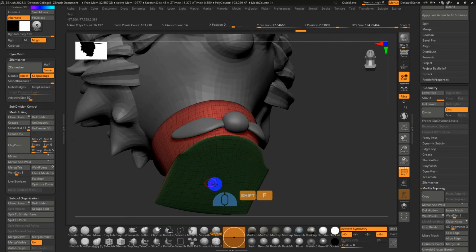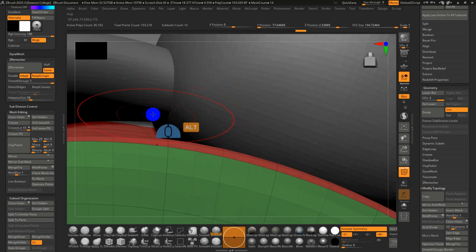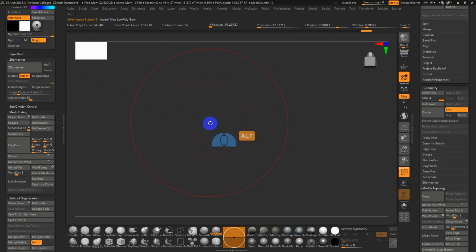If we have models that are not perfectly flat at the bottom, sometimes we get issues where the print doesn't stick to the print bed because only part of the bottom is touching, and then you have this tiny gap. So again, gaps and voids can be a bit of a problem when it comes to modeling, and you see I have a problem here with that as well, right? Between the bow and the rest of the model.